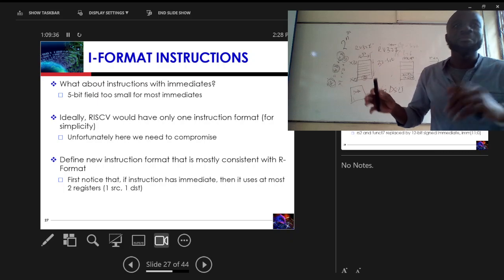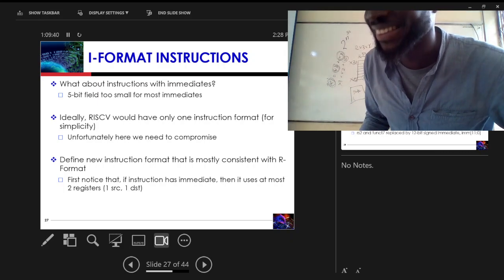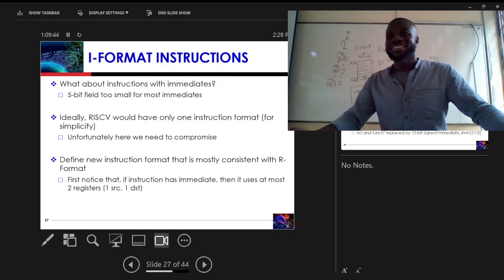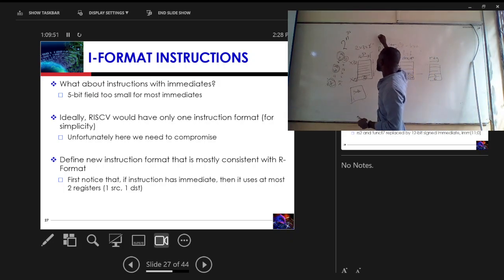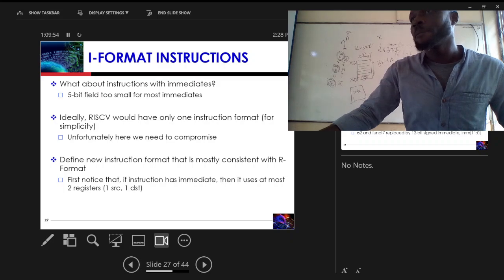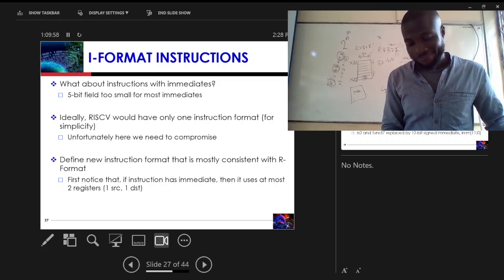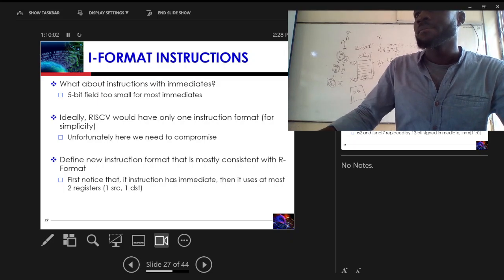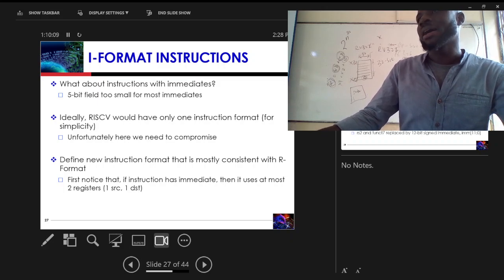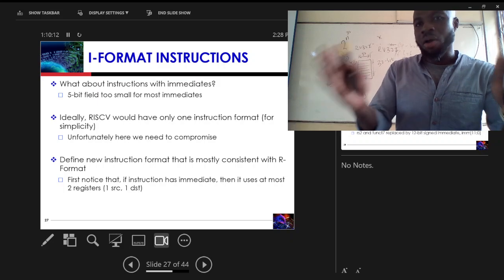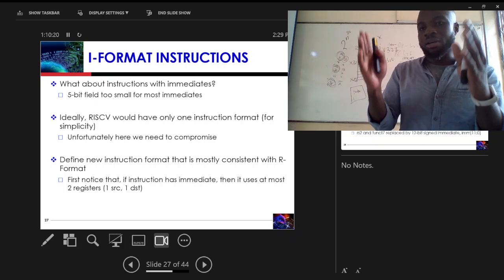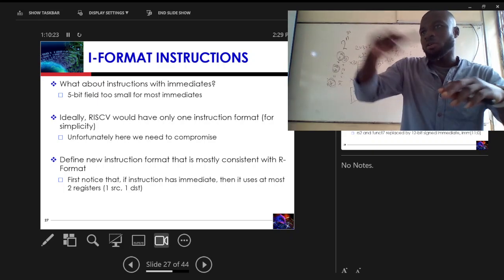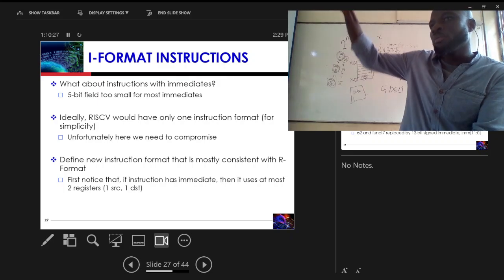Now that we know how to add numbers in registers, right? So what if the opcodes are all being the same, does it mean that they all follow a similar execution pattern? Yeah, they all follow the same execution pattern. Add, subtract, multiply. If you think about it, with add and subtract, you are dealing with three registers. You are adding one register to another, and then you are storing it in another register. Subtract and stuff like that. XOR. If I say XOR, you take one register, you XOR it with another register, and store the results in another. So they all follow the same kind of format. That's why they are all grouped together.